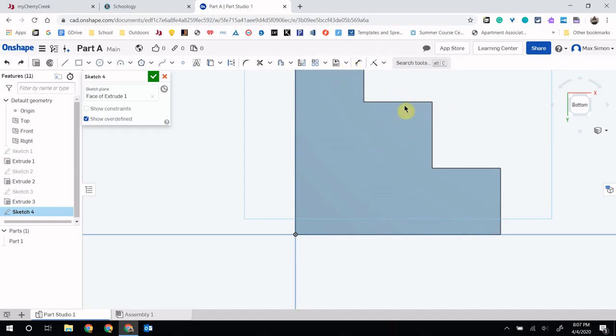If we didn't do it that way, we could also just do it with math. If you can't get these to work for you, that's okay. Let's say you just get a circle going, and you can dimension that out by clicking on the center of that circle and clicking on that line and telling it that you need it to be half of 15.